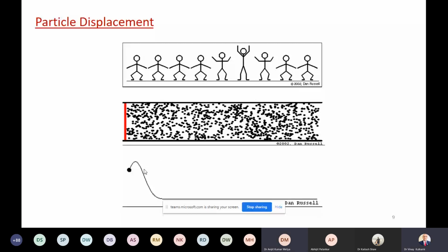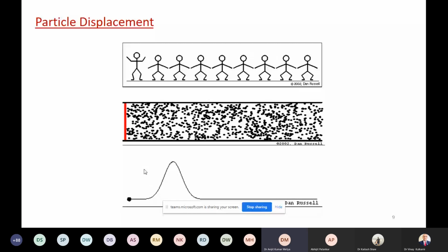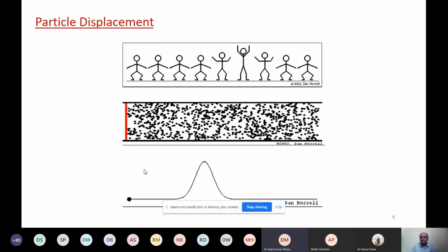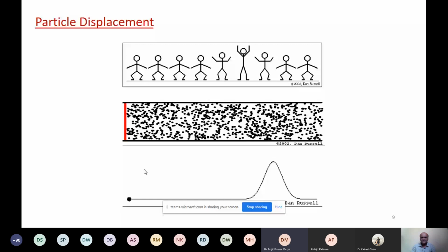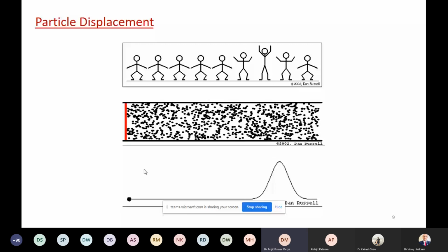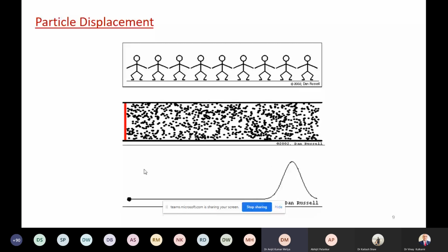Yes, this is the animation showing how a wave propagates through a material. See, every particle vibrates in its own position, but no particles move from one position to another. The acoustic energy is basically transferred from one particle to another, and the acoustic waves are propagated through it. Within that mean position, the vibration of that particle is in the elastic domain. That's why no plastic deformation occurs within the material.